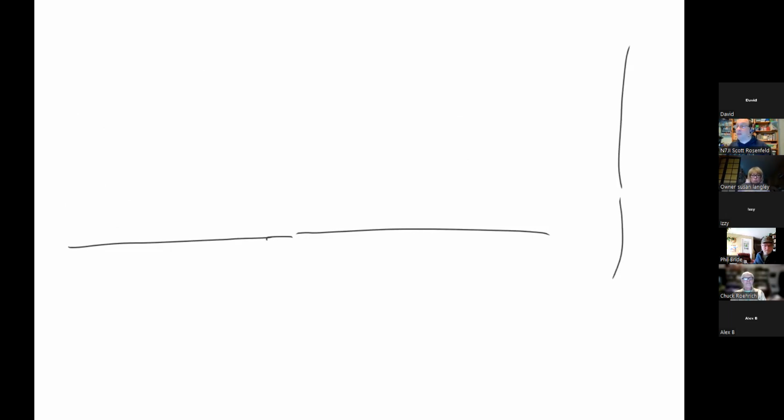It'll be a totally different antenna. The polarization will be different. This is parallel to the ground, so that's a horizontally polarized antenna. And this is vertical to the ground. So that will be a vertically polarized antenna. They're totally different antennas. Now, does it matter if I take this horizontally polarized dipole and I take it like this pencil and I roll it? Can you see any difference at all if I rotate it like this?